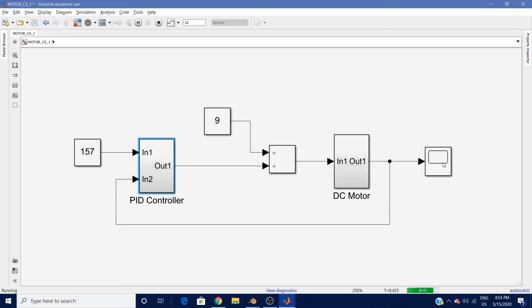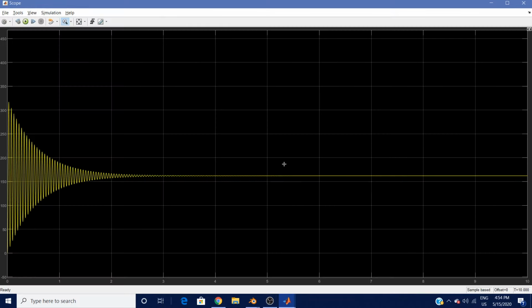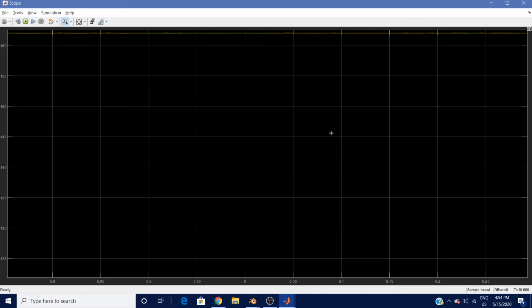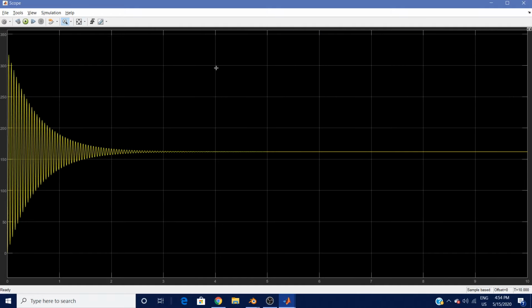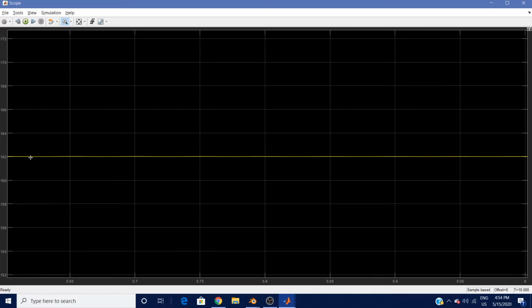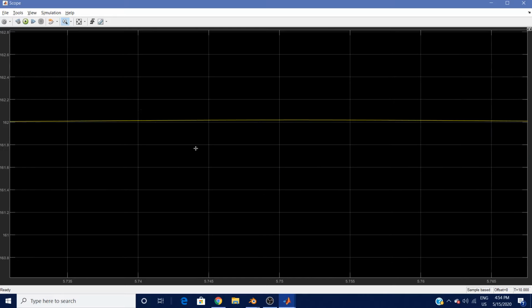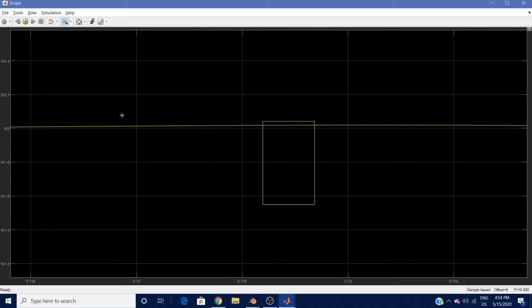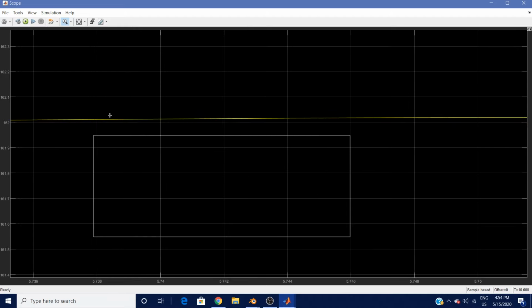we can see that the output is going to be a lot of oscillations, yes, but the output's not above 200 anymore. The steady state output is 162. It's actually 162. We did aim for 157, but there is some steady state error, which proves what we said in the previous slides. There is some steady state error because we wanted 157 as our final output. And if you actually zoom in close enough, you see that there are some other changes that are happening.